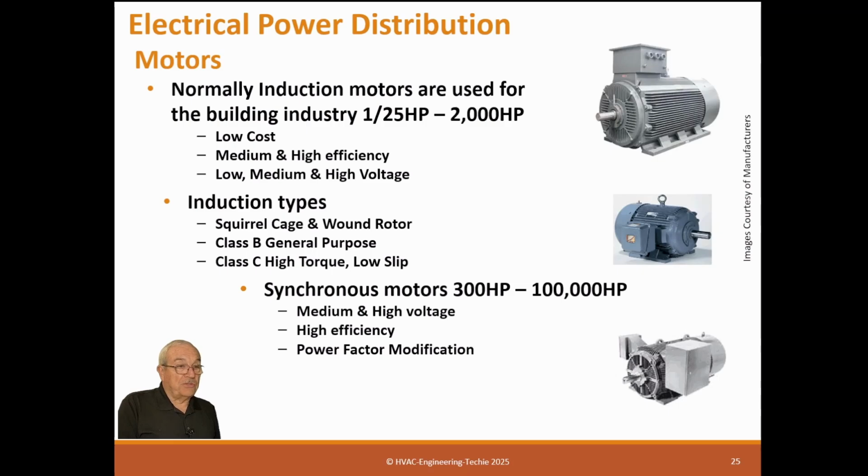Well, a synchronous motor is not that way. A synchronous motor has field windings, which have the regular AC current in them, and then the rotor has brushes putting DC current onto the rotor. And the way it's designed is that the rotor is trying to catch the stator. As the three-phase power goes through a stator winding, it's actually moving the magnetic field in a circle.